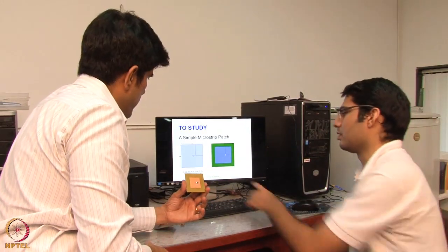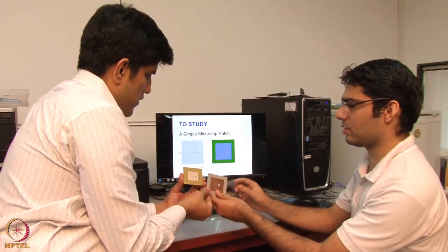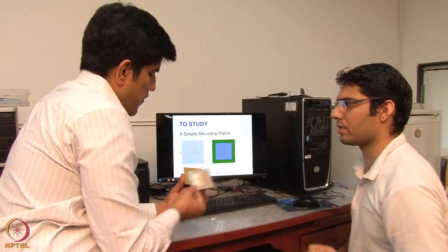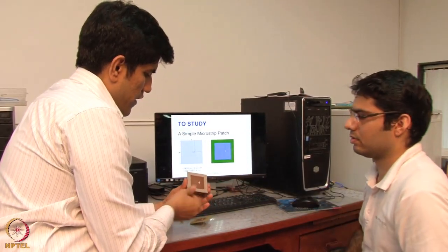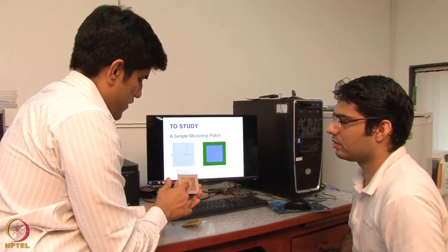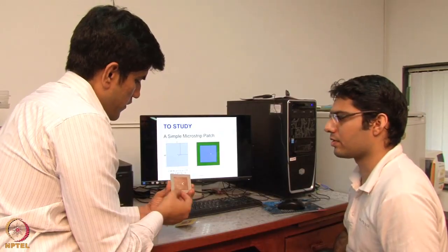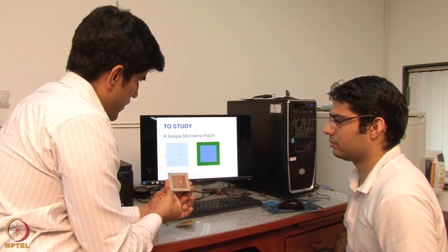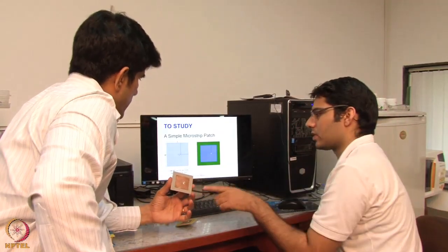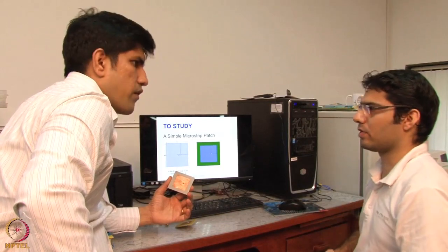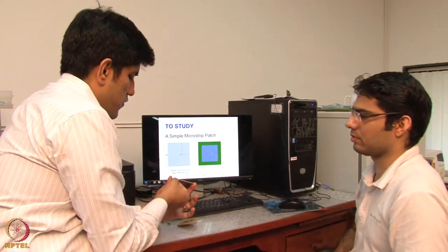And this is the dielectric constant of our material. This one is our Arlon material, and this is our FR4 substrate. We have done analysis for different substrates. So for this Arlon material, you have taken X as 7.3. Is this in centimeters or millimeters? This is in millimeters. And epsilon r is 2.55. What is this tan delta? This is the loss tangent of the substrate. It is very low, 0.0015. These are computed based on the thickness of this substrate, H, which is 1.6 mm.